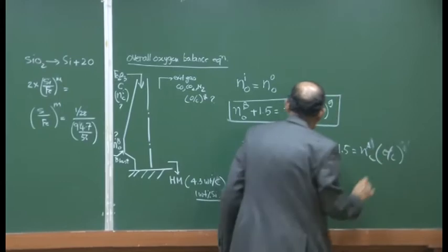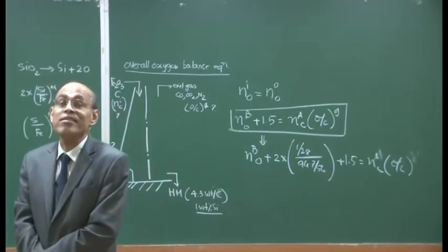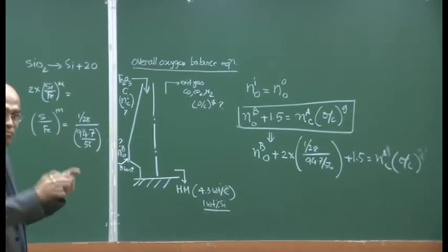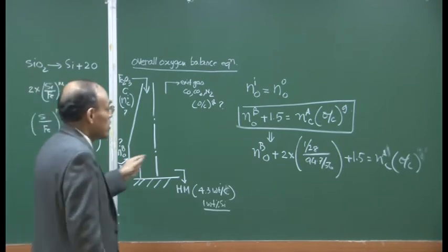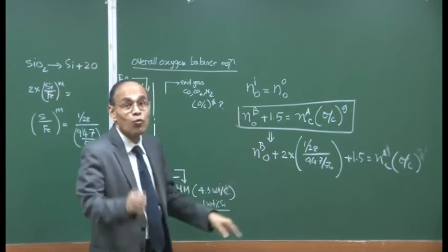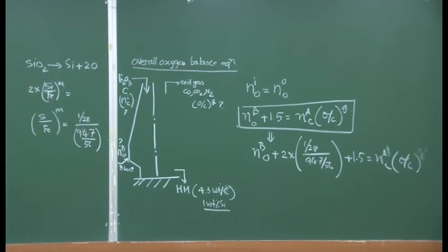Just like I have incorporated silicon, one can incorporate phosphorus reduction, one can incorporate manganese reduction, and so on. Whatever produces oxygen needs to be accommodated. We will see that when you have oxygen enrichment, this NOB value, the total blast value, will change, and the blast rate is going to change because the oxygen to nitrogen proportion is going to change also.